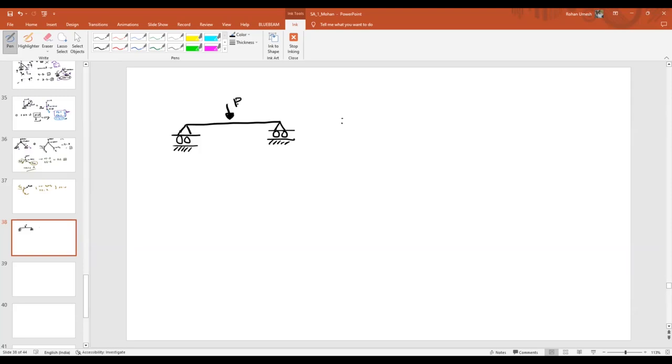A vertical force is given, so this force can easily be balanced by the vertical reactions at the supports. As horizontal forces are not acting here, there is no need to consider summation Fx equal to 0, a waste of time. Why? Because as no forces are acting, why would you waste your time considering the summation of x equal to 0?